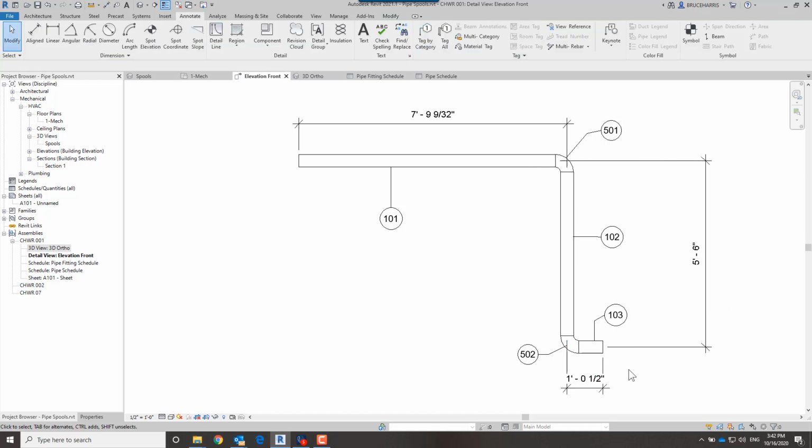Now, you may have different conventions on how you dimension, and if you dimension in the ISO view, it does get a lot more complicated. That we may have to wait for another 4-Minute Friday to get into, because you're probably going to have to edit the individual pieces and make something that makes it a little bit easier for you to grab the right plane when you're dimensioning an isometric view.